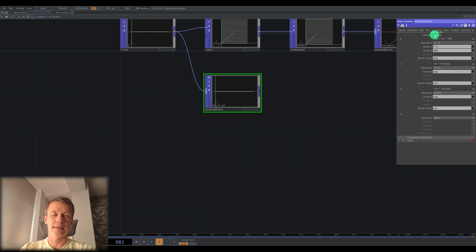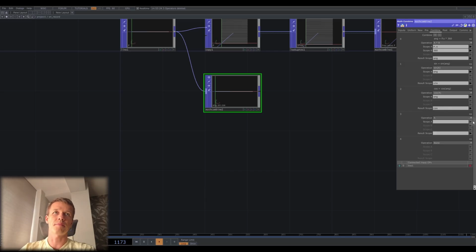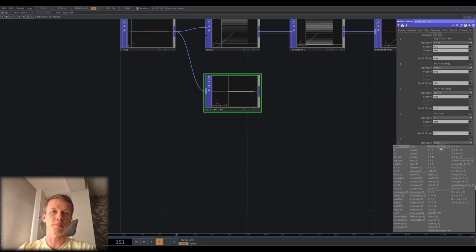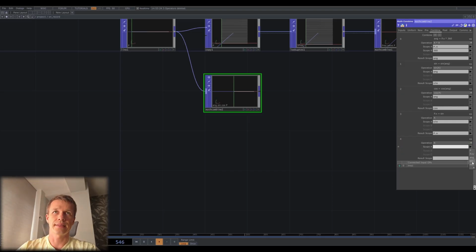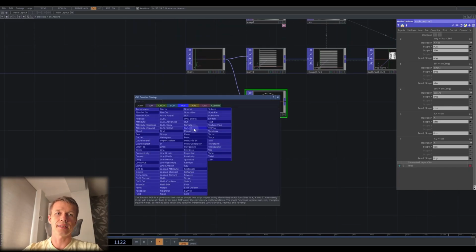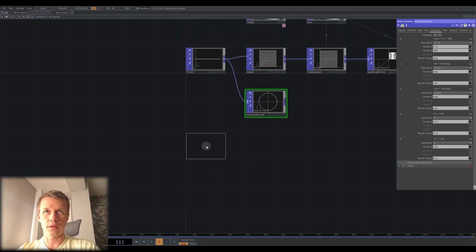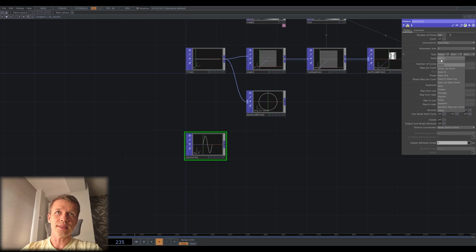I can do it with the same line using the math combine, but for this part I prefer to start from pattern POP. I set x to the cosine and y to sine, and when both use the same number of cycles and the same phase, they create a circle. Cosine controls one axis of the circle, and the sine function controls the other axis.